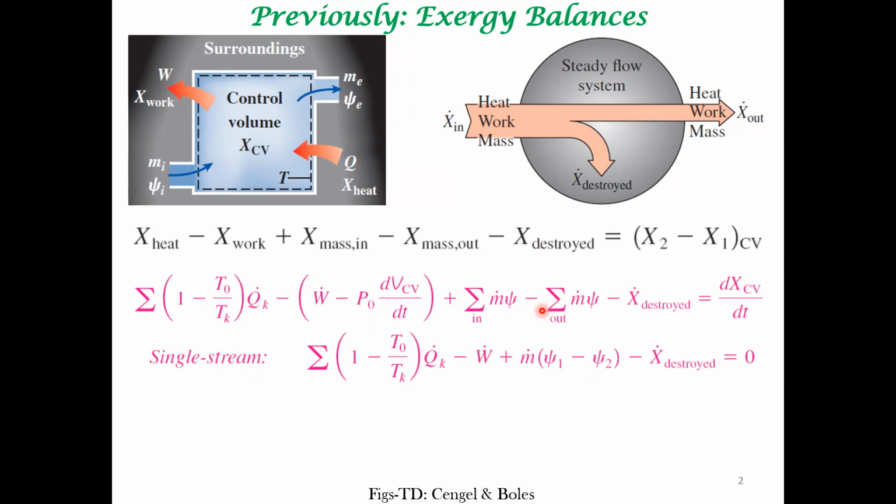The computational procedure which you adopt should take this into account. That's why the two TdS relationships were very critical for entropy balance.